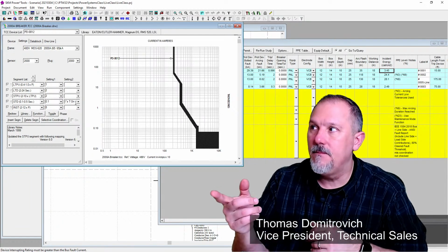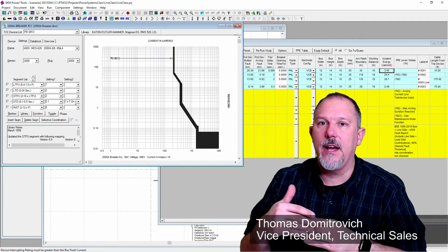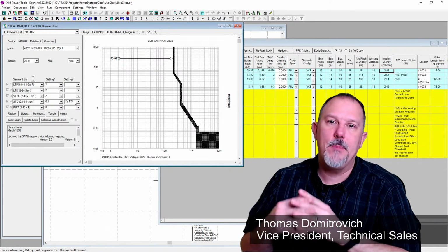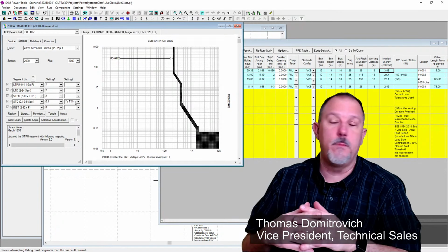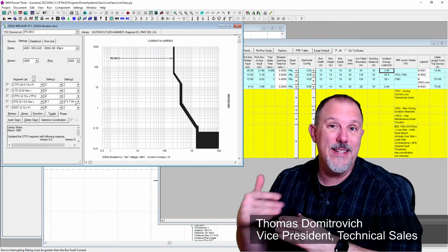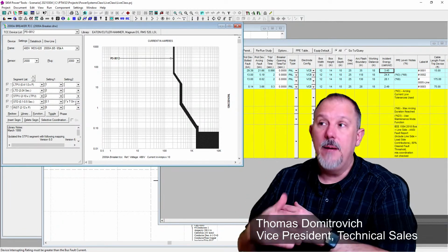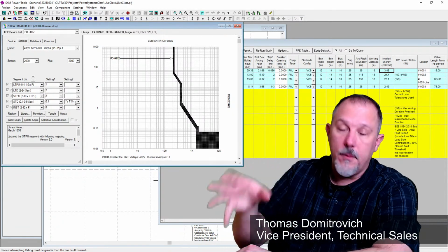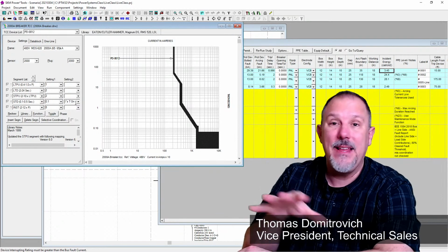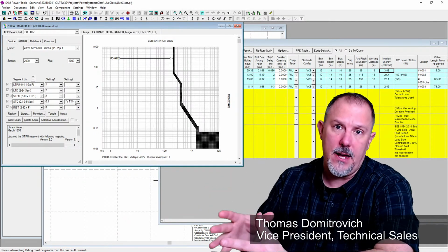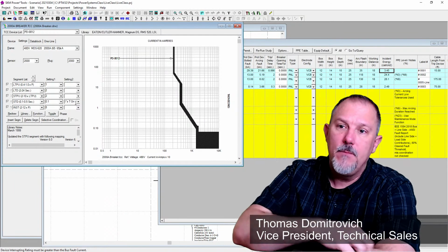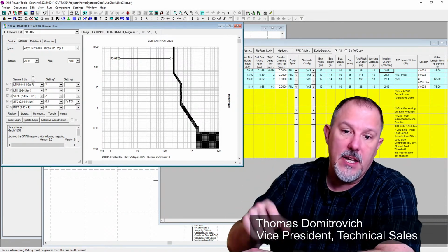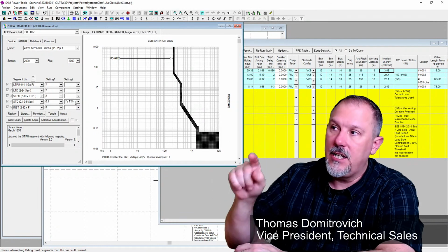With this, I can be at 3.45 calories all the time, regardless. If anything happens in that equipment when I'm not in maintenance mode, I will always have a low incident energy. But I had to buy a bigger breaker and go to a more expensive trip unit to get that flexibility and functionality. Now, I bet my application engineers in our sales offices will probably get you a better mix to get that addressed.